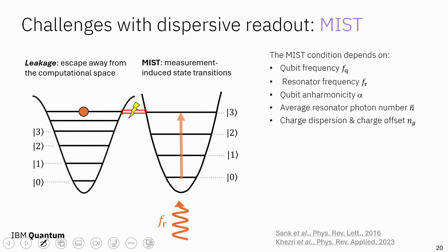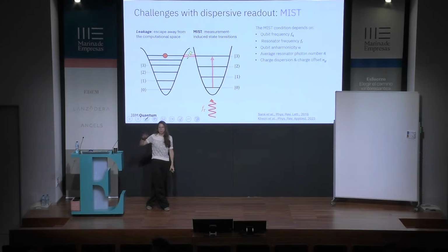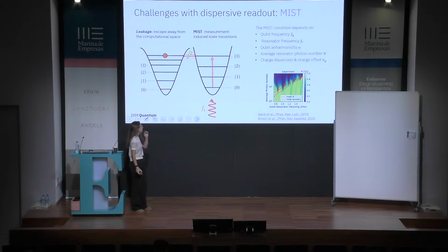So you remember that we work at some regime for which the transmon bands are perfectly flat in offset charge. This happens for low energies, but the very high up ones actually still retain some relevant charge dispersion, so that even maximizes a bit more the probability of having these transitions.